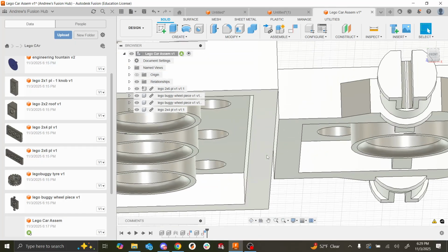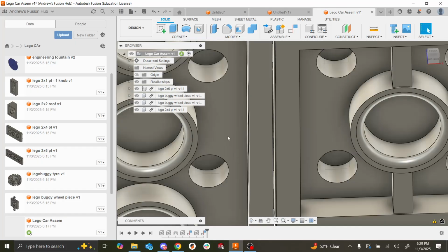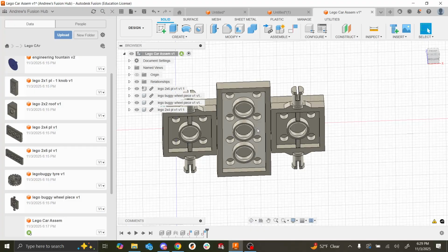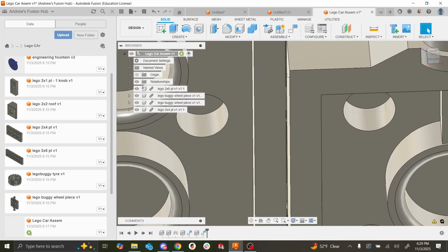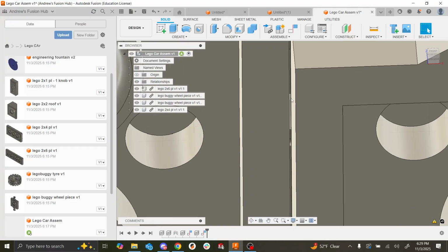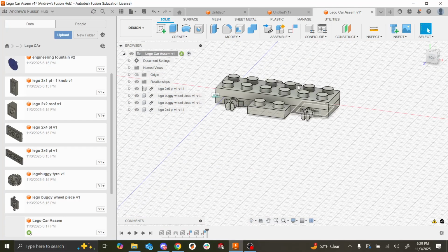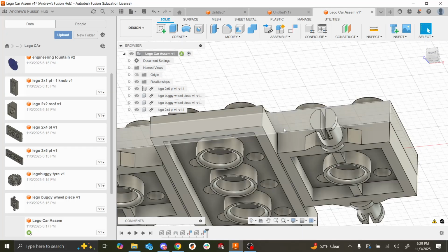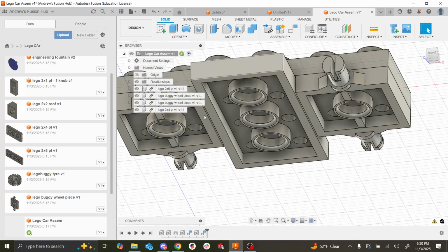Yeah, okay. So you can see here, in this Lego model, these cylinders should be concentric with each other. So this is placed correctly, but you can see there's this really tiny gap here. And it's kind of hard to know what that gap is unless you design these parts, which we didn't. So if you were to use the joint tool and then constrain it edge to edge, this gap isn't going to exist unless you create an offset, but that offset is unknown. So that's why in cases like this, I think the constraint tool kind of comes out on top.